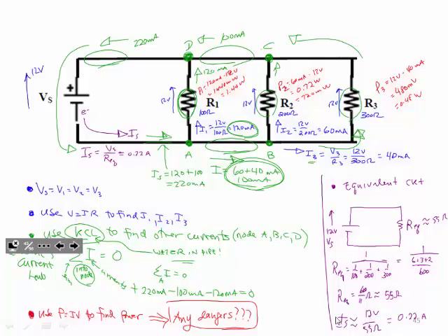So I've got 1 over 100 plus 1 over 200 plus 1 over 300. If you like fractions, you can get a common denominator on these in the bottom of 600. And I got 6 plus 3 plus 2 over 600, which is 11 over 600. And take the reciprocal of that. I got 600 over 11 is 54.545454 repeating. Or I could just toss this all in my calculator at once, and in the end I get the same thing.